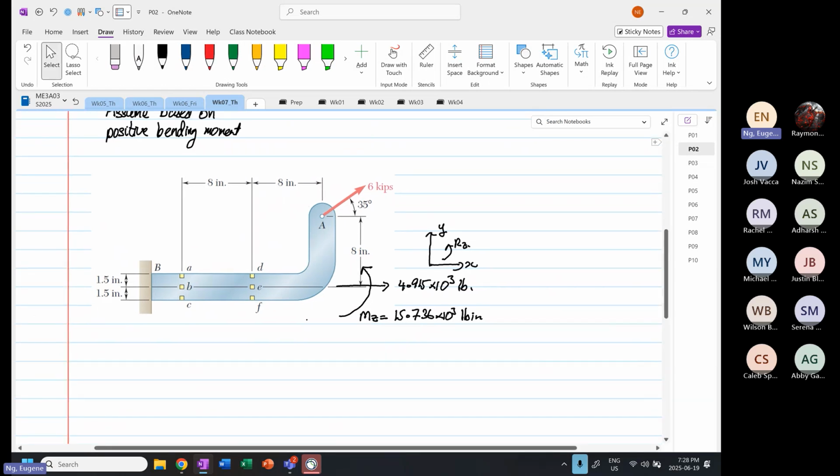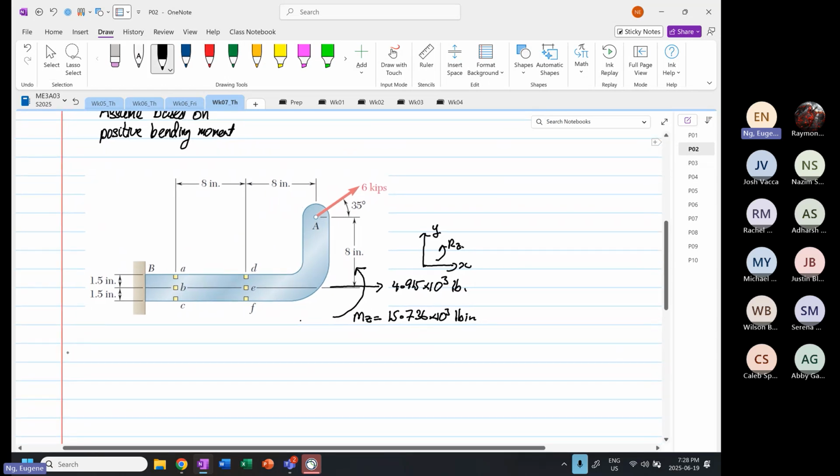Yes. So from here, if we look at our formula, we know stress X is equal to plus minus Px over A, plus minus My over Iyy multiplied by Z, plus minus Mz over Izz multiplied by Y. Since we only have Mz, My is equal to 0.